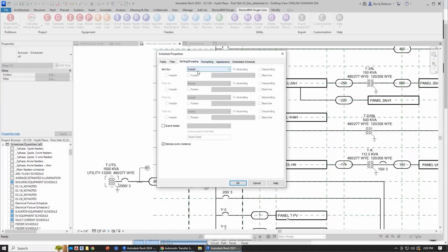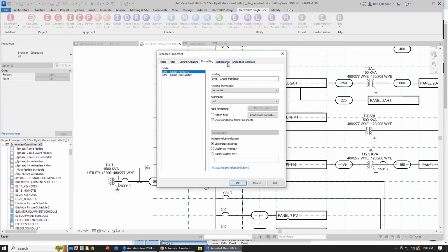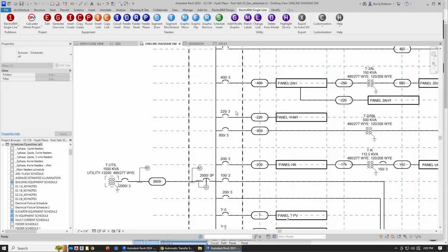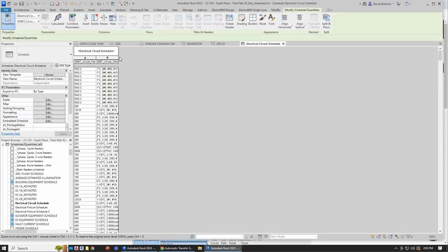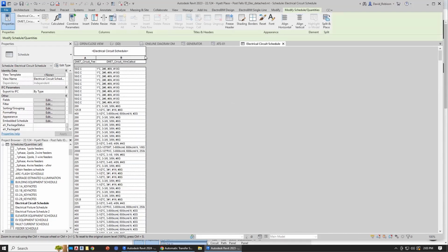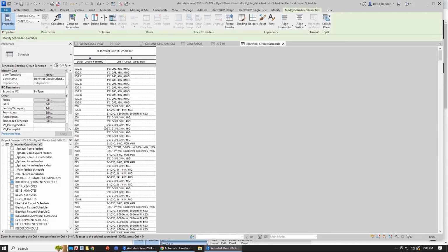And I think we can probably group them. I can't remember how you do that. But anyway, if we do this, I'll just click OK. It'll be close enough. No, it'll be a schedule of those. Yeah, I see what you mean. Yeah, so you have this schedule. So this would be the way you could create it as a standard Revit schedule. And then sort them and group them by this ID so that you don't have all the duplicates. And then that way you can have this schedule. I like it. It's under sorting.